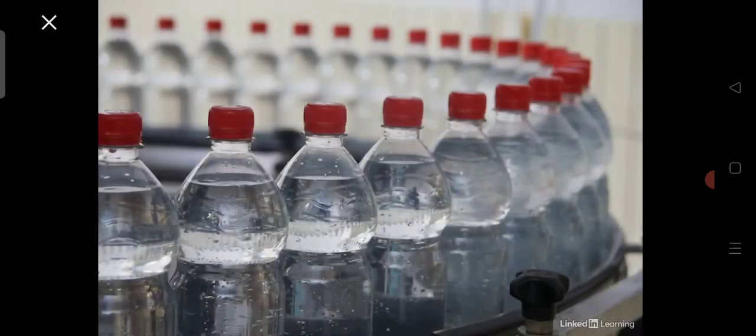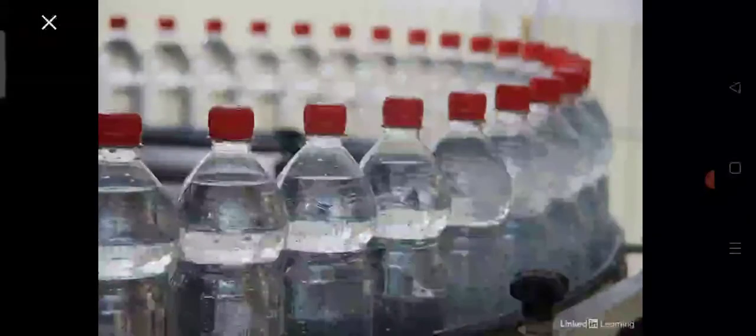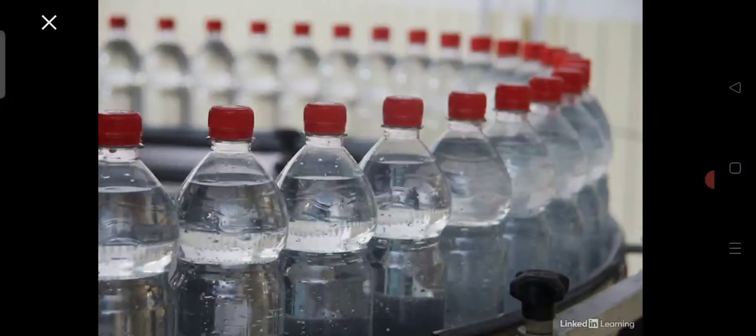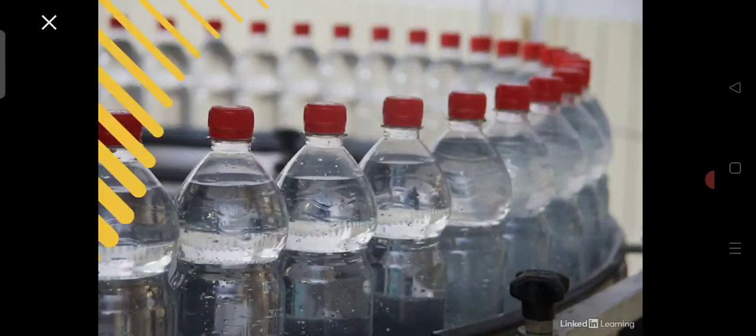Liquid targets generally have a higher dielectric constant that makes capacitive sensors a very common option to use within food and beverage industry and chemical processes because of their extreme sensitivity to liquid targets. Glass and plastic have a low dielectric constant value that makes them one of the best options as common materials to be used for the containers when using capacitive proximity sensors.